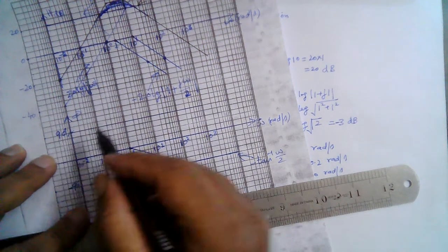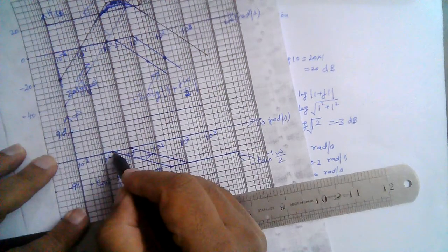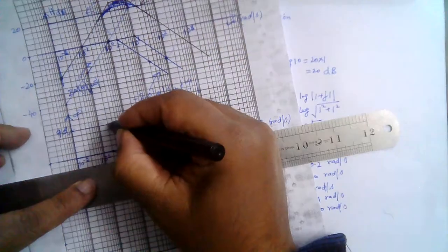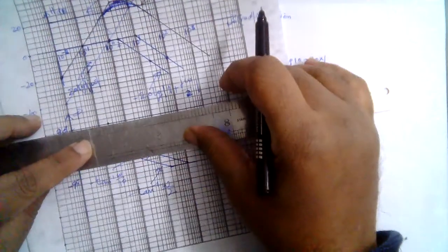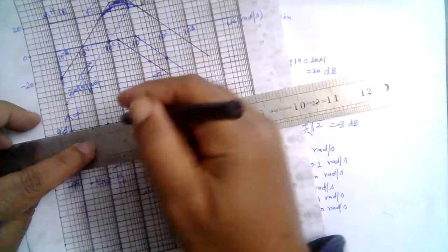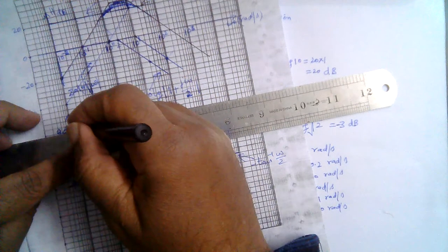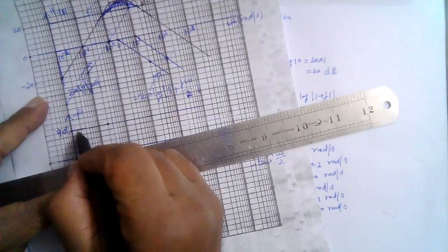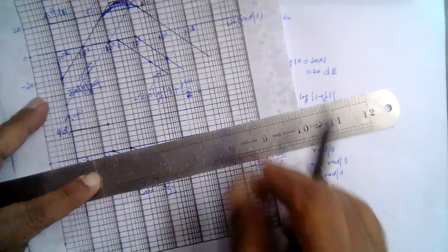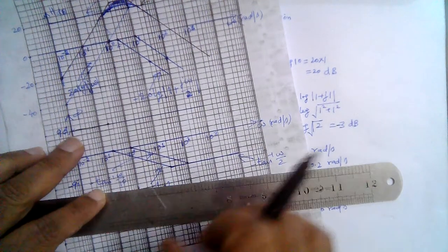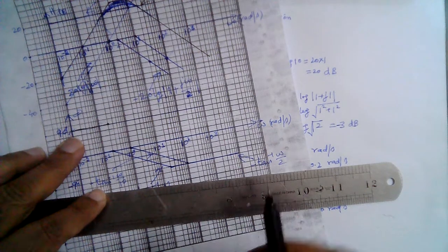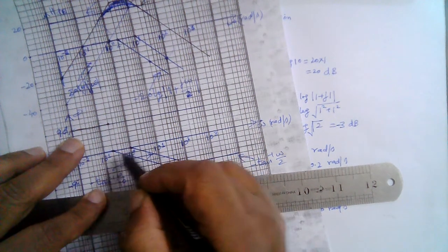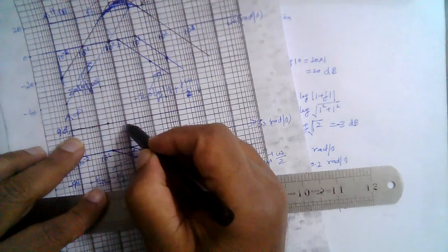So we begin at 90 degrees till this break frequency, right? Till this first frequency here, we have this constant line at 90 degrees. Then it has a slope of minus 45 degrees per decade, a line parallel to this line till this point, right?